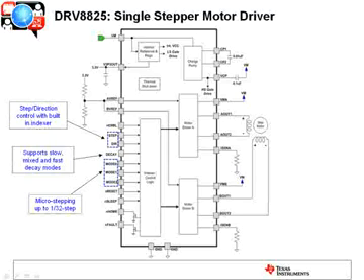In terms of microstepping, you have 3 pins here that'll set the step size, and it'll support up to 32 microsteps. So it's got a built-in indexer and control logic. It's got a lookup table, and it knows all the correct currents and polarity to generate that microstep, 1/32 or even 1/16 or 1/8 and so forth, or even a full step. But that's all built in. You don't need any type of external processor. You just need a signal to drive that step and direction.